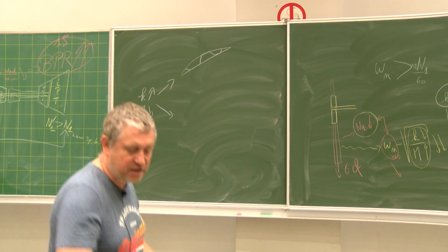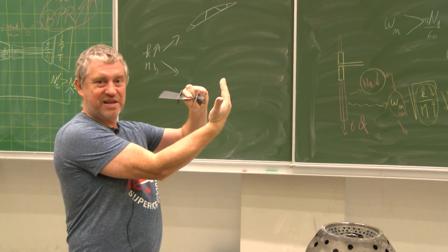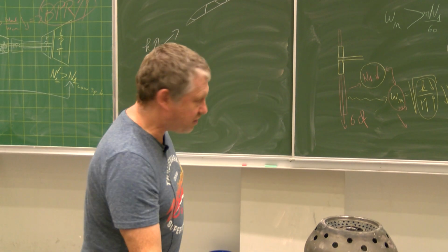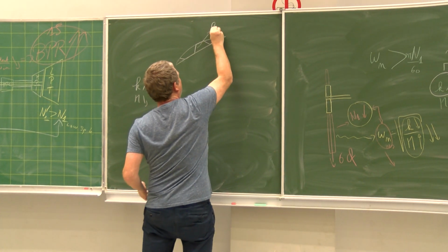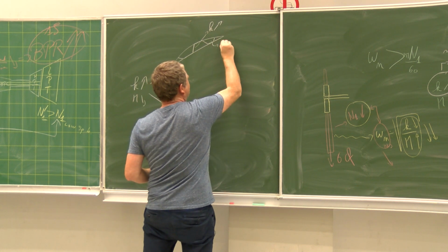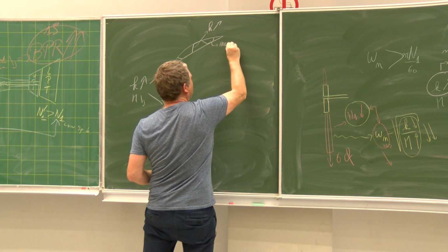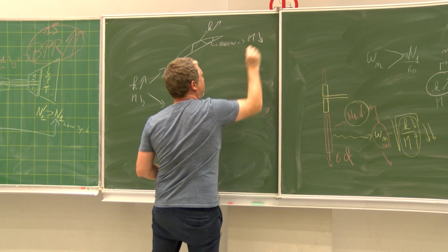If you take this blade, here it's empty and you can see your hand on the other side. Of course, you see that thanks to the stiffener, you have increased the stiffness, and by the fact that it's hollow, you have largely decreased the mass.